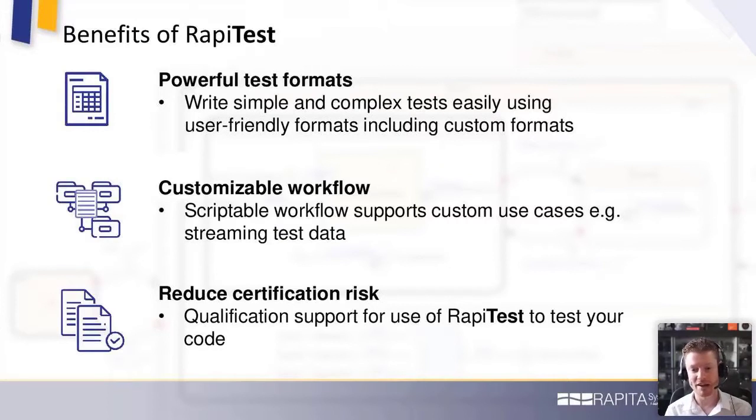Normally, we would compile the test vectors into the source code itself, which is the easiest way to get ultimate portability, so you can combine an executable with all the test data in it that you can run on host or target or anywhere. But sometimes, if you have very large volumes of test data, very large tables, for example, it's not appropriate to compile that in. So we have methods where we can send that data to and from the target in order to complete that sort of testing.